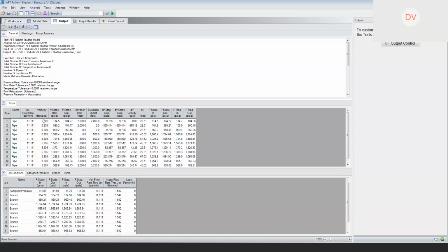So we want to keep a velocity below 8 feet per second, but also higher than 2 feet per second. So we've already set the diameter of the line at 30 inch, but when we start looking at the zero-based execution, the velocity for the minimum and maximum should be considered. So pay attention to this during ZBE.